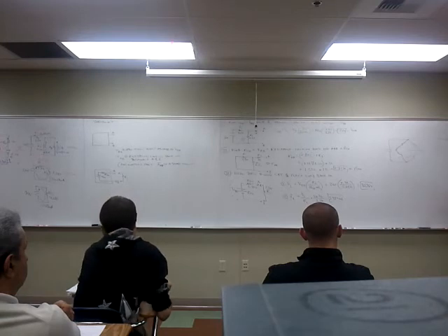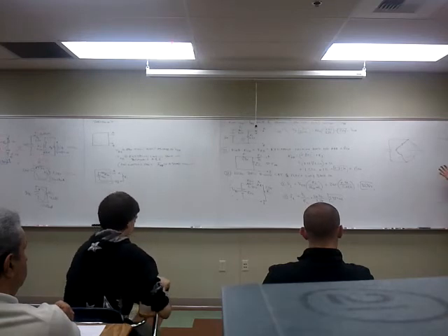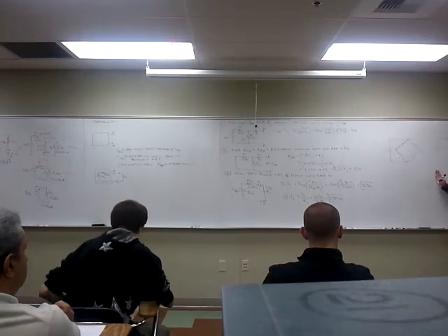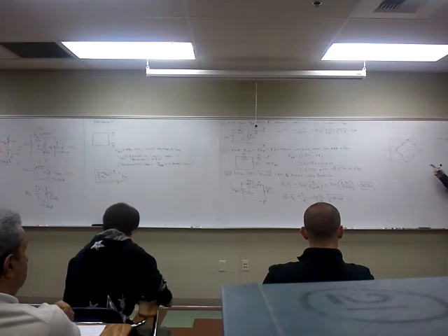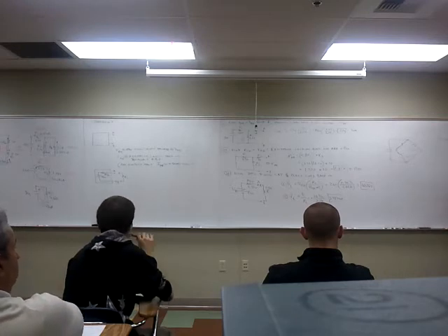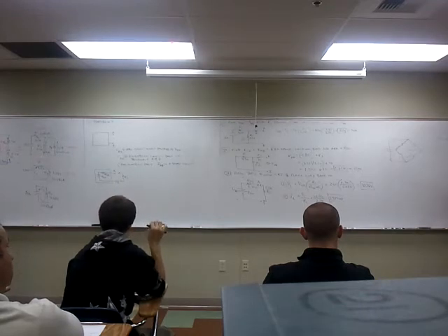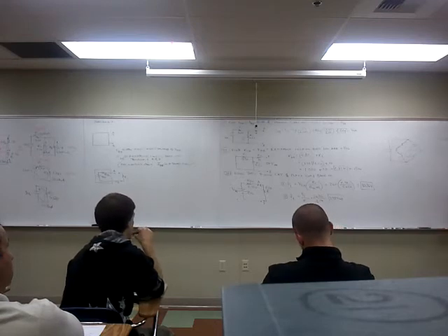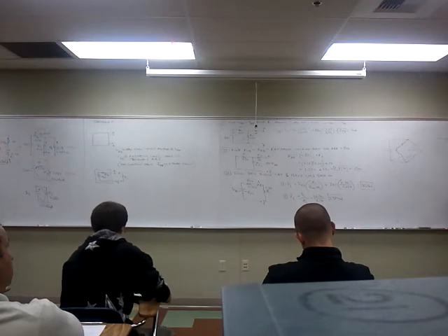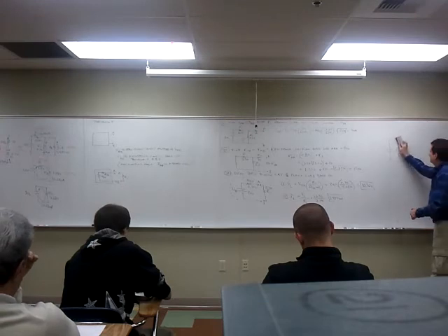The reason I'm bringing this all up now is you may be wondering, why am I going through all this? But believe me, you save huge amounts of time knowing these theorems. You'll find later with Norton, you can have a transistor amplifier, and if you make the output the Norton equivalent, it makes it incredibly simple because the transistor by its very nature is a constant current source. And if you understand Norton, you save a huge amount of calculating and you have a better understanding, which is the main thing. So it's the reason behind the madness.